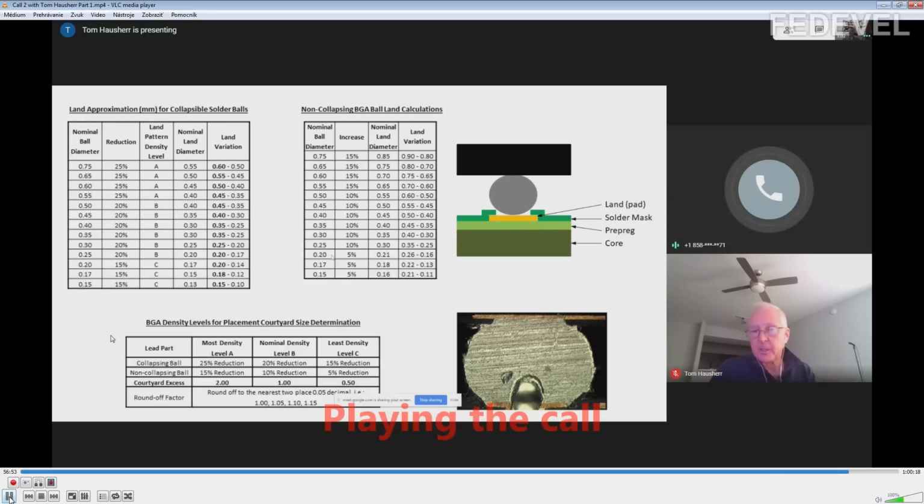And then when the manufacturer engineers told Dieter Bergman about the stress tests, the drop tests, okay, the vibration and the shock, when they drop a Motorola phone, that the pad rips away from the prepreg, Dieter Bergman says, oh, I know what you're using the solder mask for. You're using the solder mask to hold the pad down to the prepreg. If you have to do that to pass your drop test, go for it. I'm so sorry that we said don't solder mask. Solder mask defining a BGA pad is wrong. It's bad. Don't ever do it. And Dieter Bergman changed his mind after talking to these people who actually do it. That's why we're saying that not everybody follows IPC, because IPC says some things that don't make any sense.